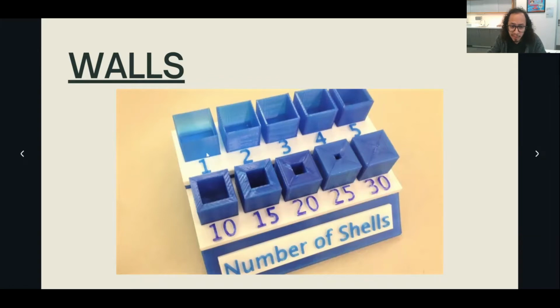I personally don't do one. It's really cool because it's a little bit translucent, but I haven't had any luck printing with it. So I usually do 2 or 3, and then that'll be good enough for your regular everyday prints. If you're wanting something a bit more sturdy, you can increase the number of shells. And then to also increase the durability of your object, you can increase the shells and increase the infill, which will make it more solid.